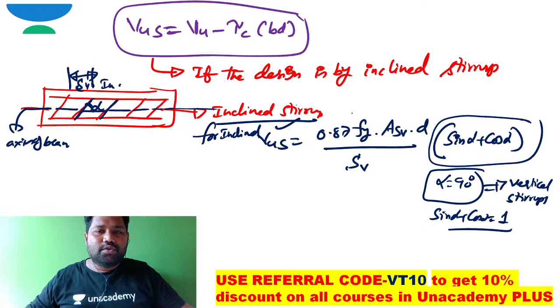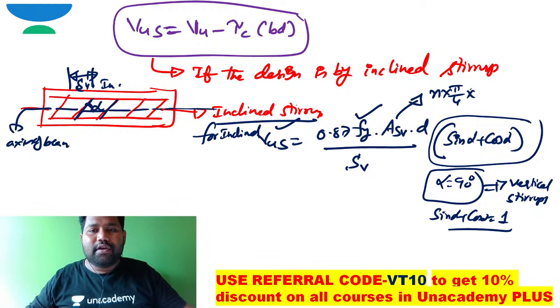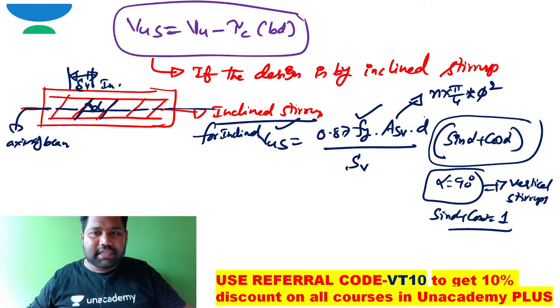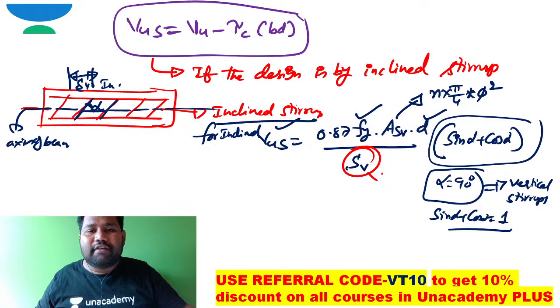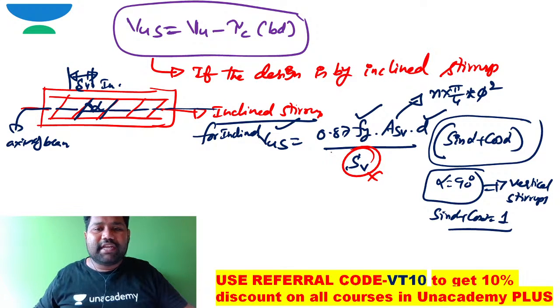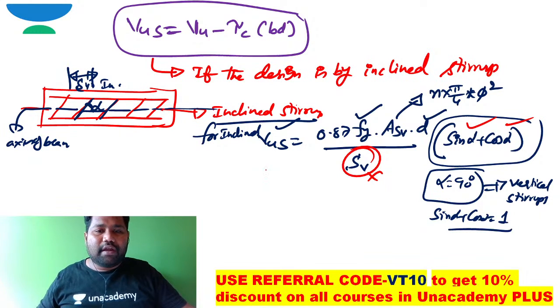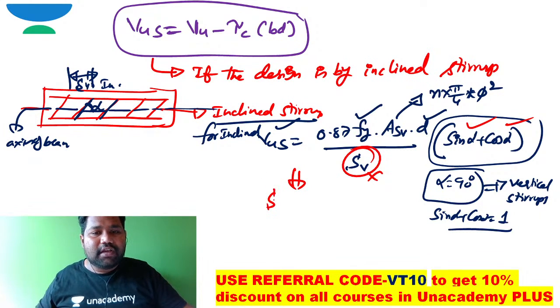You know Vus, you know Fy maybe 250, and Asv. It is two-legged stirrups, so I can write n into pi by 4 into diameter square, say two-legged 8 millimeter stirrups. d is the effective depth, and Sv is the spacing of the shear reinforcement, which I need to design using these inclined stirrups. Alpha, sine alpha and cos alpha will also be known. So from this I can work out the spacing of inclined stirrups.